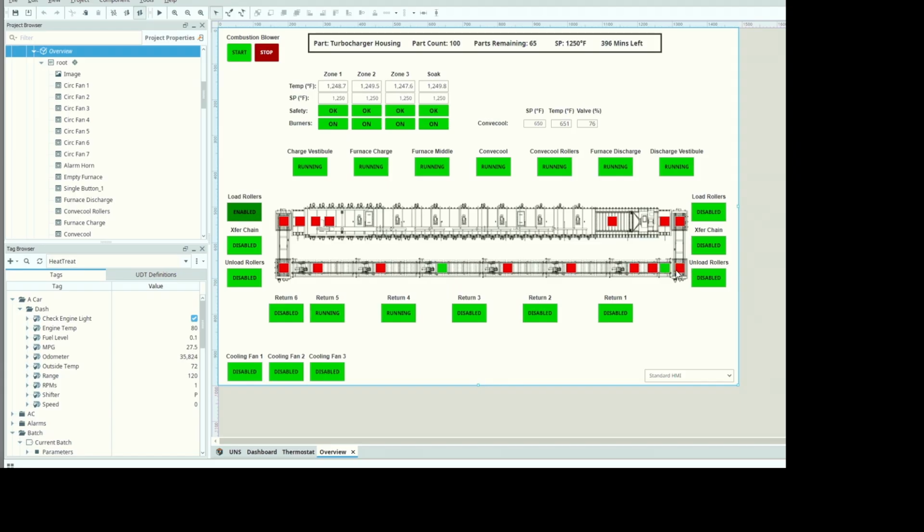We'll also see here, each one of these red squares is a position on the conveyance system. There's a photo eye, which is basically a sensor that detects if something is in the way of the photo eye to indicate if there is a pallet in that position, indicated by green, or if there is no pallet in that position, indicated by red. And then between the positions here on the bottom, we see different motor graphics. Those would be motors similar to the engine in a car that we can control whether they're on or off with a start or stop signal, similar to the ignition in a car.